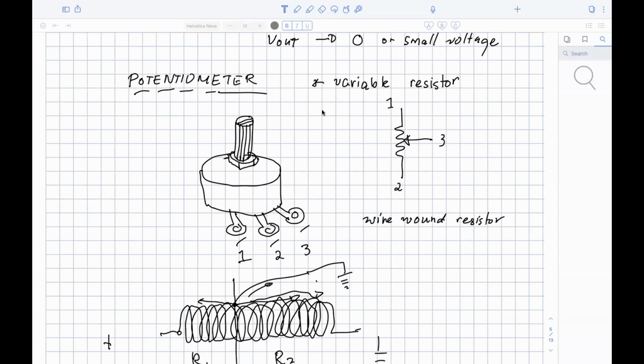Imagine sticking a popsicle stick on this knob. Okay? But what we need to do is we first have to calibrate. If you measure this voltage out, what angle is that? If you measure this voltage out, what angle is that? And we will have, therefore, an input-output curve. The input is the angle and the output is the voltage. So this is our first experiment.